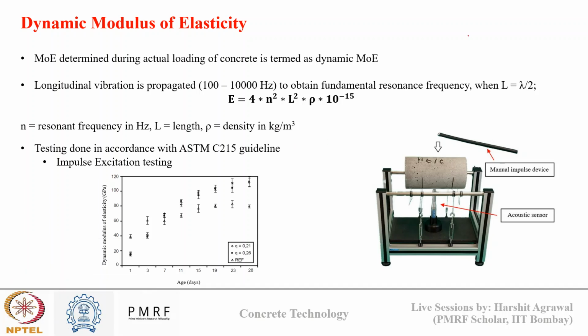Instead of using a static load, we apply a longitudinal vibration on the concrete sample within the frequency range of 100 to 10,000 hertz. This allows us to obtain a resonating frequency, which depends upon the length of the sample, and which is equal to half of the wavelength.